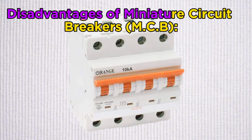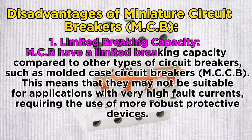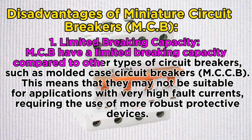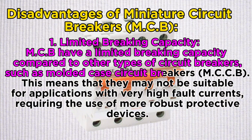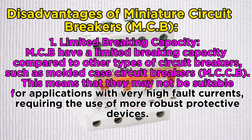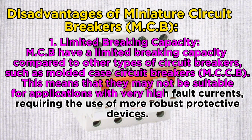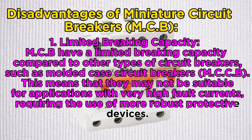Disadvantages of miniature circuit breakers, MCB. 1. Limited breaking capacity. MCBs have a limited breaking capacity compared to other types of circuit breakers, such as molded case circuit breakers (MCCB). This means that they may not be suitable for applications with very high fault currents, requiring the use of more robust protective devices.